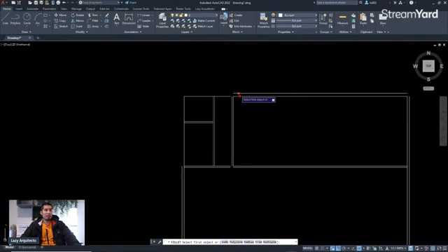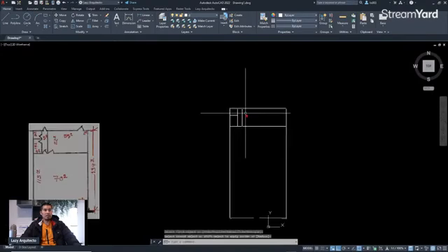And the fillet command, what it does is it connects two lines. Following the instructions on the command line, it says select first object. So I'm gonna click this, and then second object, I'm gonna click this. You can see that it will connect those two lines like so.